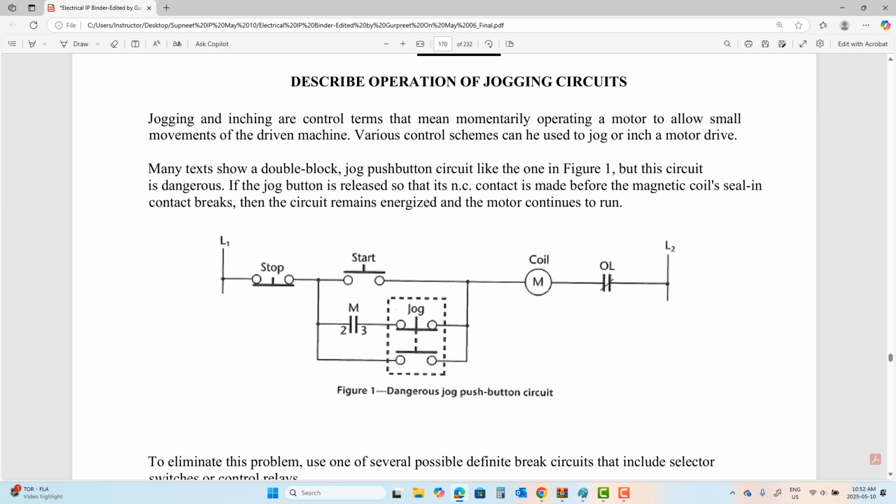So they jog, they stop. They jog, they stop. During an application of a jogging circuit for an elevator motor, the contacts close, open, close, and they're not getting time to cool down. Somebody presses the button, they go to the second floor, the 20th floor, second floor, 20th floor. That is called a jogging circuit. So in a jogging circuit application, your contacts have a chance to get welded because they don't get much time to cool down.